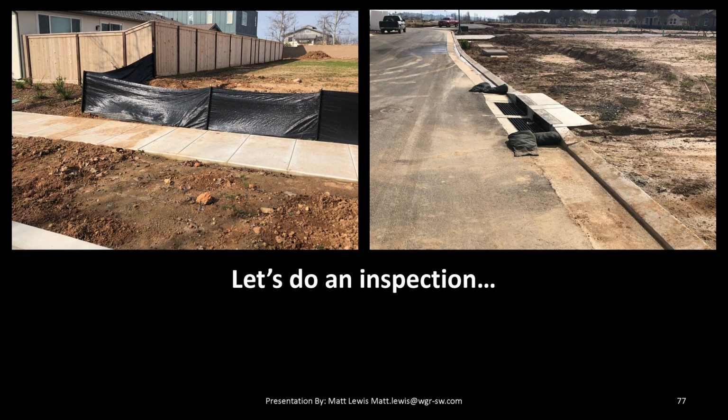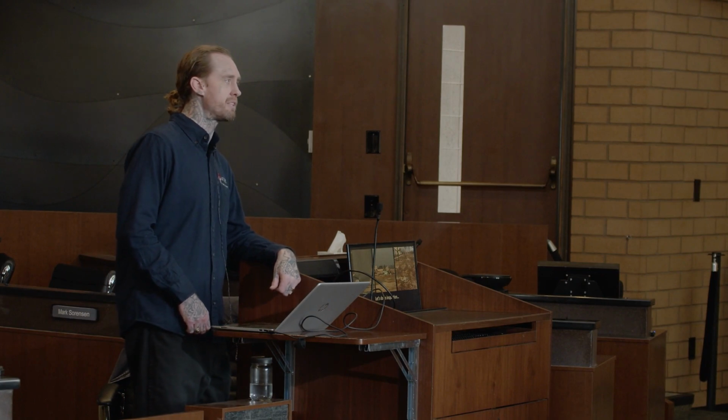They've got tons of sediment in the curb and gutter, and their track out is all over the place. They got exposed soil that's longer than 14 days of inactivity. And if I'm not mistaken, it's a bit hard to tell, but there's even some concrete washout there next to the curb. Believe it or not, this is the last slide.